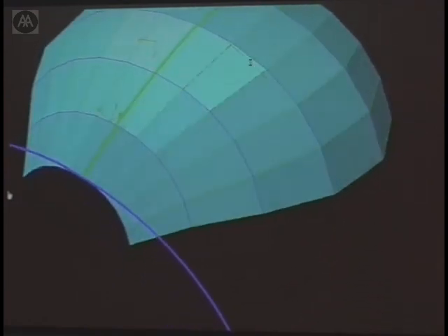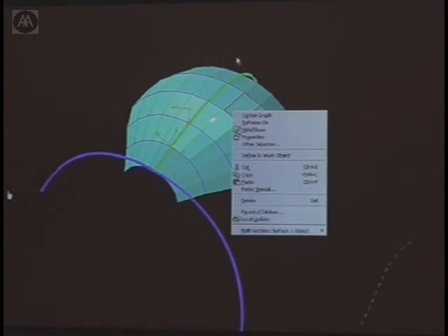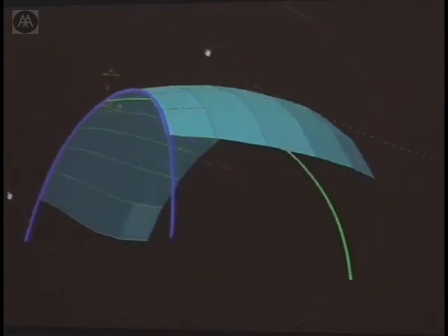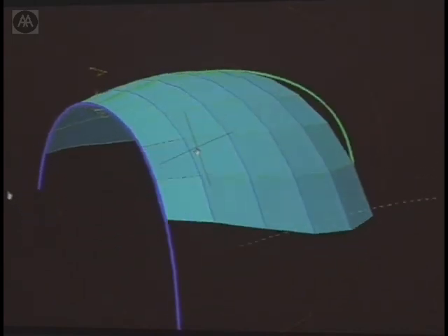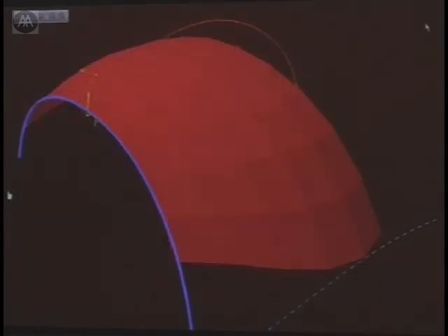which now you could cost again. And suddenly, basically, what is the advantage of this system? Well, you've eliminated a third of the mullions. You've gotten rid of these diagonal pieces. You've greatly simplified the node joint, which is expensive. But also importantly, you have eliminated these triangular corners, which leads to a lot of shards of glass.